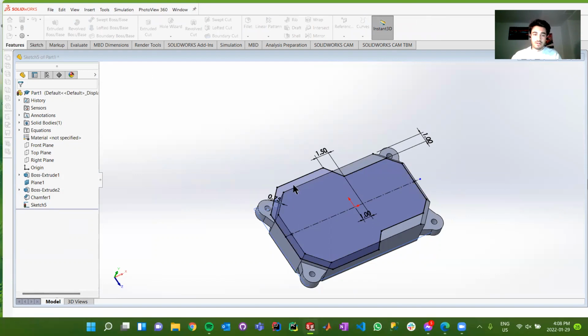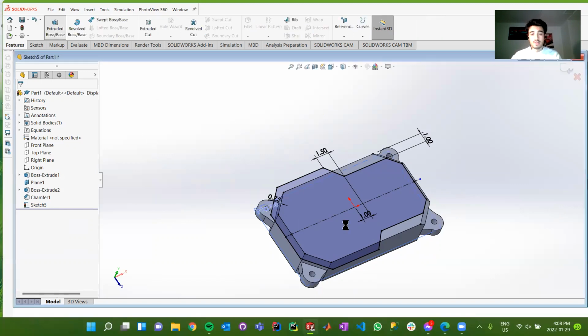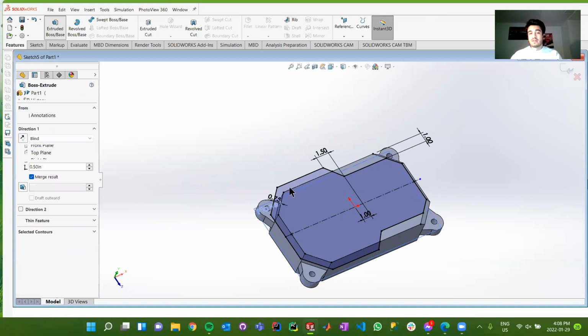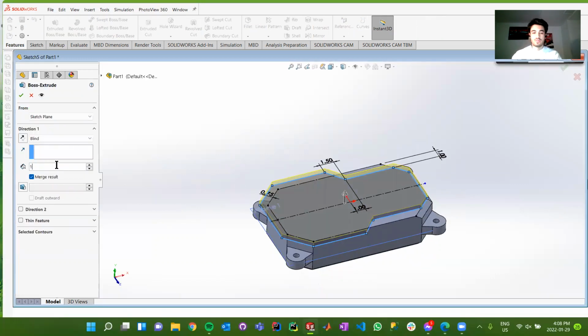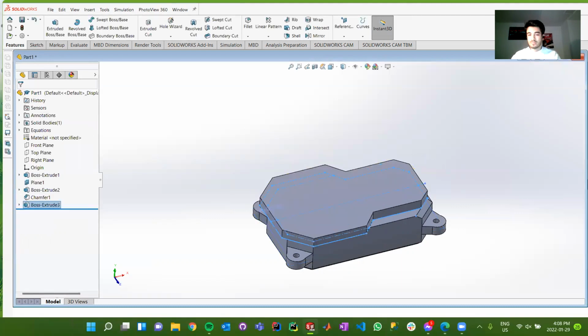Going to click on our contour right here. Ooh, sorry, my apologies. My other monitor got in the way. Click extrude, contour, awesome, and we'll just go up by 1 inch. Nice. And we have the option to merge if we want, so we could do that. I'm going to do that. We'll keep it like so, just so that it's one composite part.